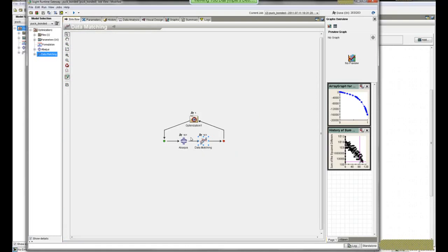Again, the end result is that Isight finds a very good set of coefficients. I can see that graphically by the y-squared difference going down tremendously. I can also see it because my target value and my simulation value of the compressive force now line up pretty much line on line. Now I can go back and do the rest of my simulation work with these good coefficients. And I think with that, it's probably a good time to open up the floor to questions again.